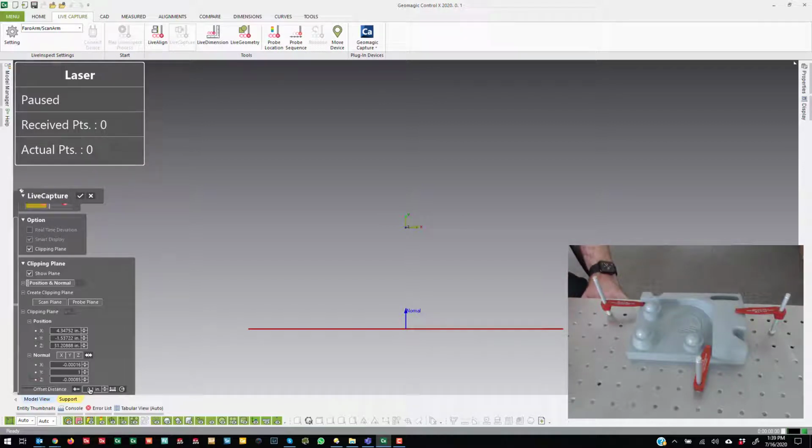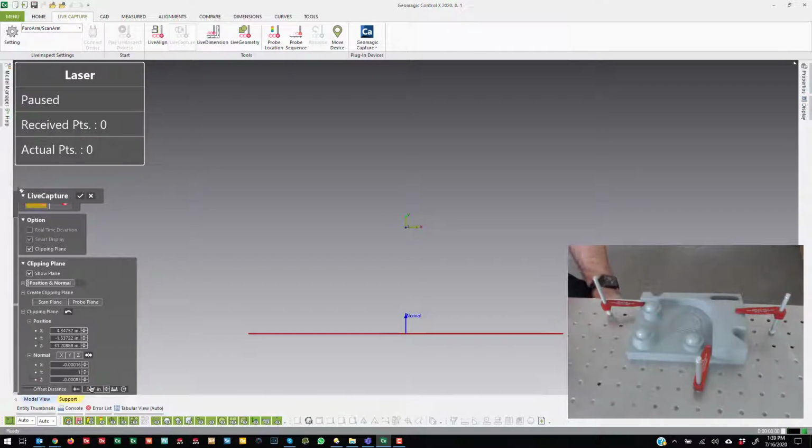And you want it to crop out all of that data. So here is 0.1. That's a little bit high, because that's 0.1 inches. So I'll just leave it at like 0.03, like 30 thousandths. That's good enough for me.